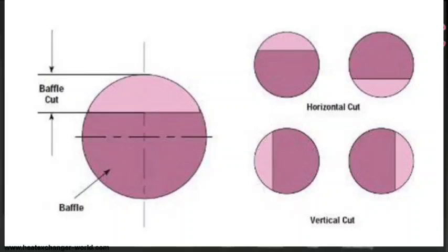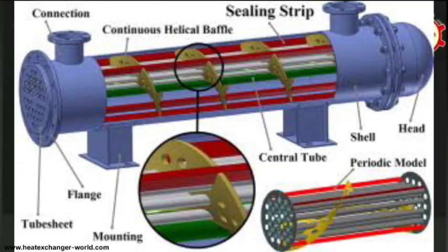But as Kaushik said, if somebody goes to site, cutting the baffles is not much work. I think you just have to remove it from inside, open the bolts, remove it outside and cut. No, it's a fixed type, na. It is fixed type and seal welded. Okay, then again you have to cut the complete vessel. Rather than that, you can prepare a new vessel.